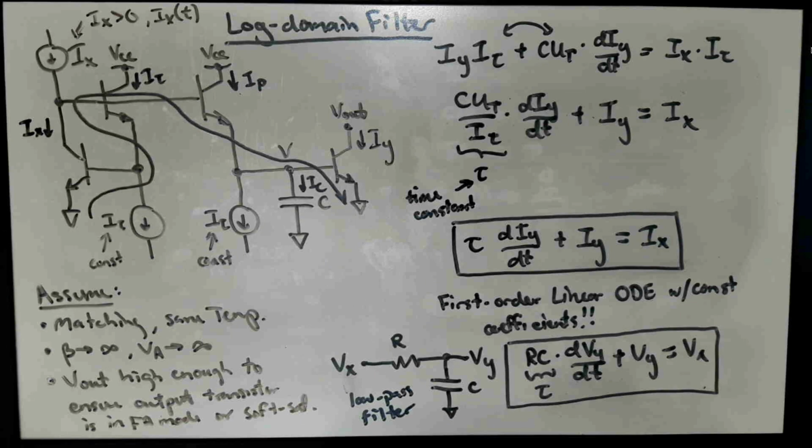You basically put down a layer of conductive material, you pattern it using a photolithographic process, then you put down an insulator, you put down another layer of conductor, you pattern that second layer of conductor, you then put down a second layer of insulator, third layer of conductor, pattern the third layer of conductor, and so it's all these little sandwiches of conductive material separated by insulators, and that's a capacitor. So capacitors are very easy to integrate.